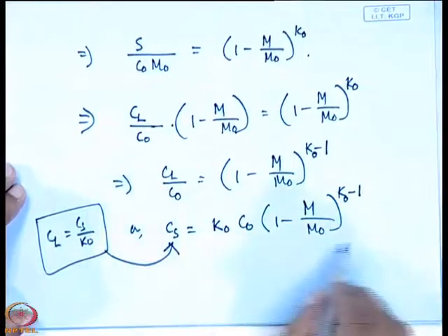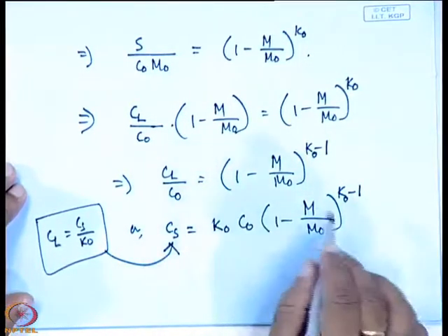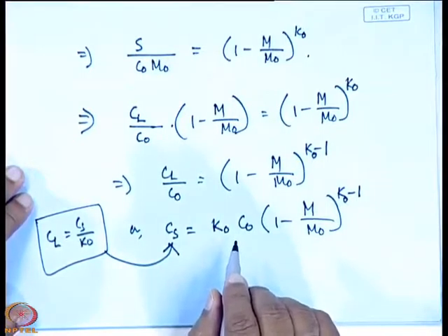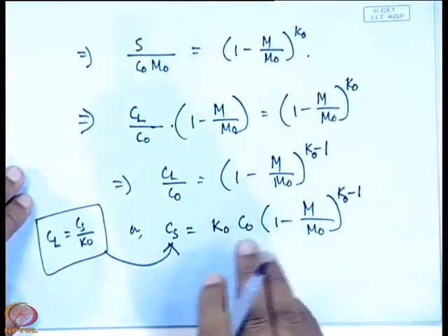Right. So, this is the expression for the dopant distribution in a float zone technique, and this distribution is applicable for any kind of crystal growth where the doping takes place.